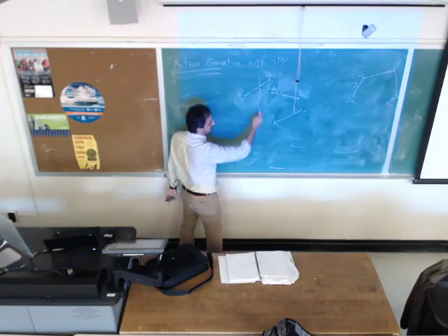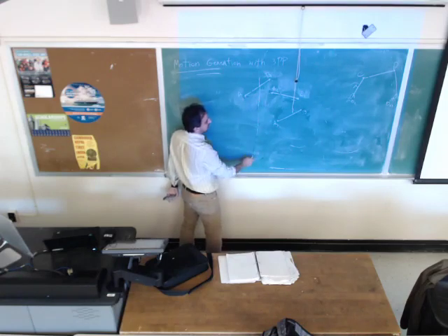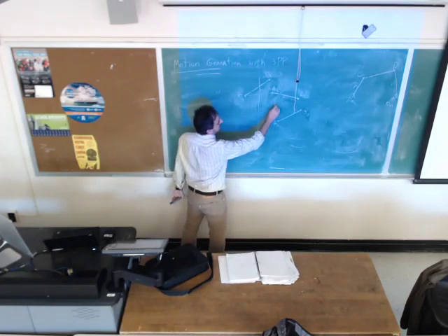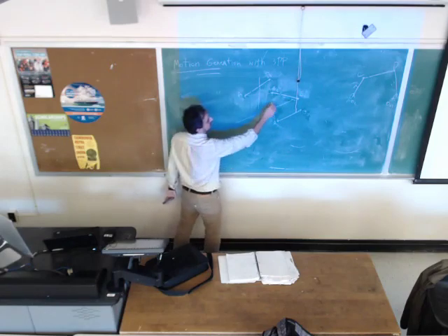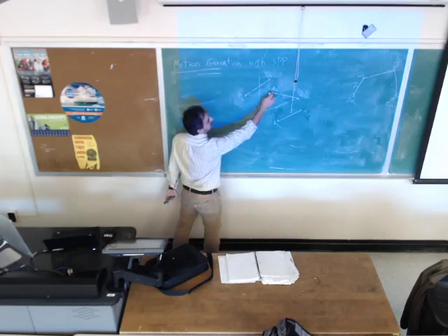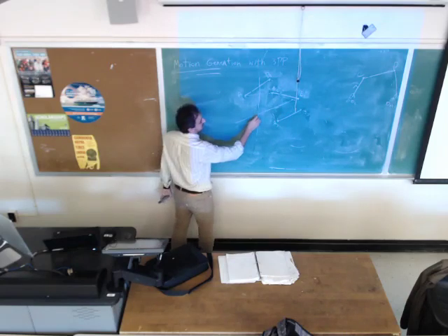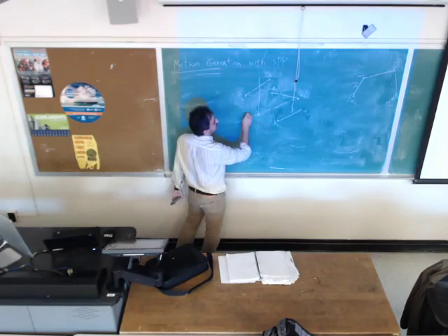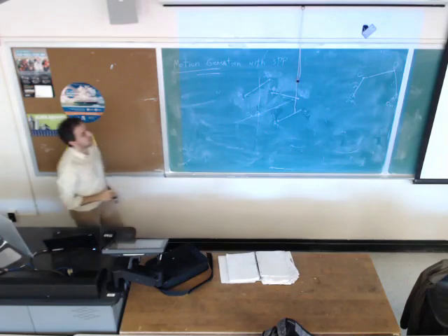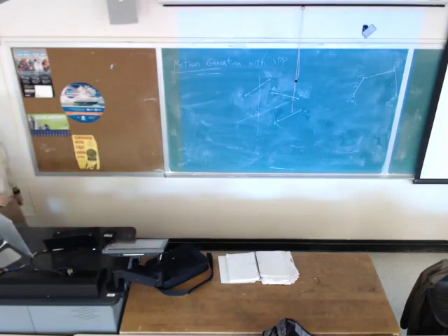So I know that O2 is going to be on this line. At the same time, I know that O2 is going to be located on the perpendicular bisector between A2, A3. So the intersection of these two lines is going to give me the location of O2. So basically there are no free choices left for me.